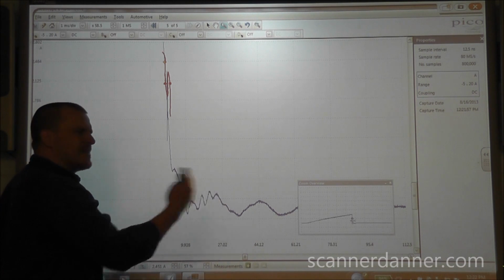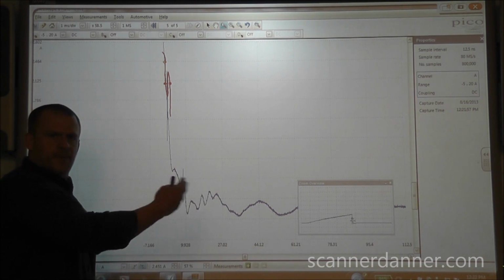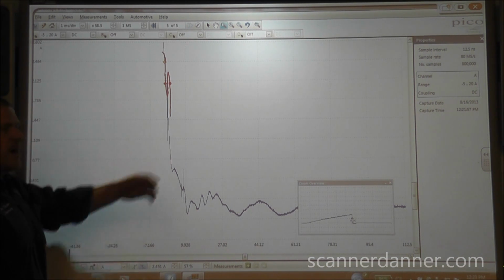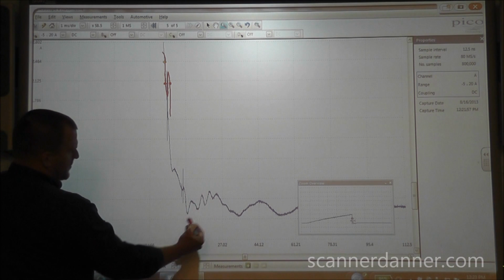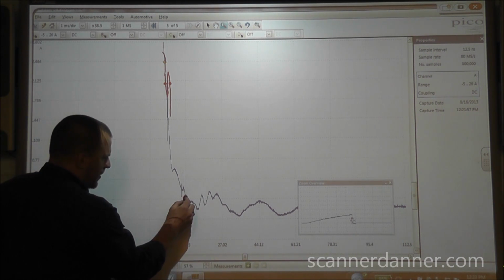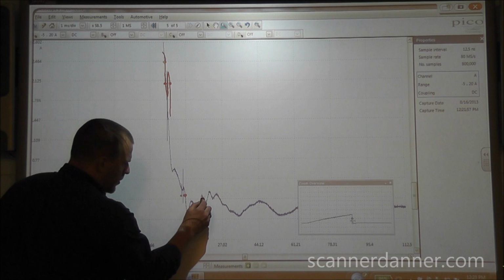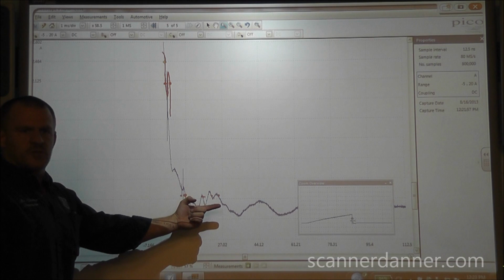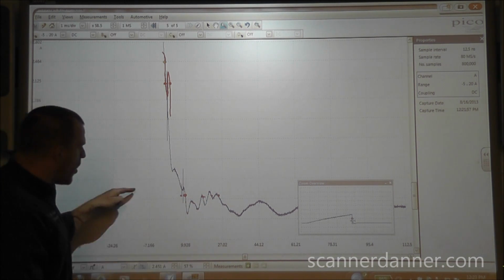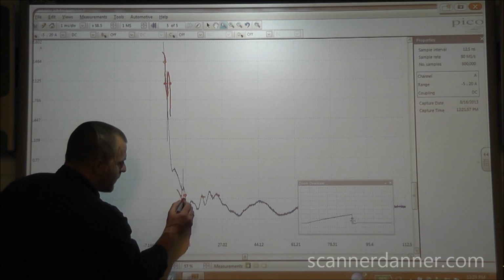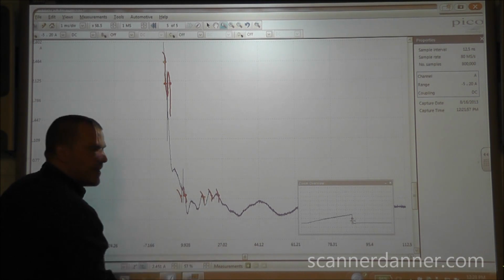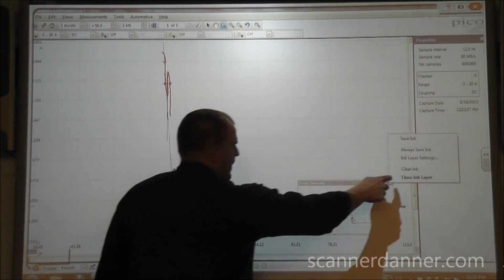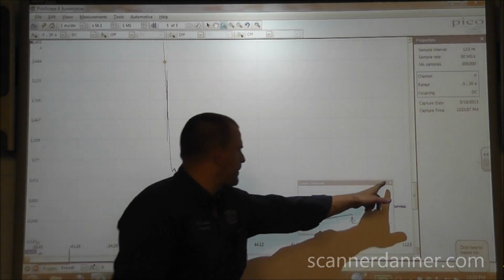Did you see earlier how at times the signal was blipping on me? That was exactly why. I would want to stay away from that kind of setting for a trigger. If I set it down in here, it's going to be even worse. If I put it in this area, there's one here, there's one here, here, and here. There's 5 different places that scope can choose to draw that picture. They're all at the same level, and they're all falling edge signals at the same level. Let me show it to you. Let's see what it looks like. We'll set our trigger down into that range and see what it looks like.